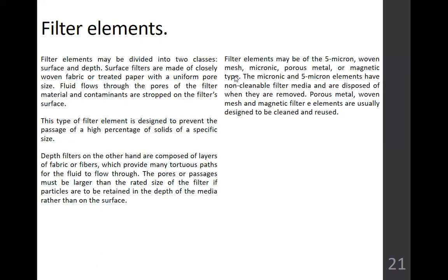Filter elements may be of the 5-micron, woven mesh, micronic, porous metal, or magnetic type. So, ibang discussion na ng filters filtration. So, the micronic and 5 microns have non-cleanable filter media and are disposed of when they are removed. So, tapon na. Porous metal, woven mesh, and magnetic filter elements are usually designed to be cleaned and reused.